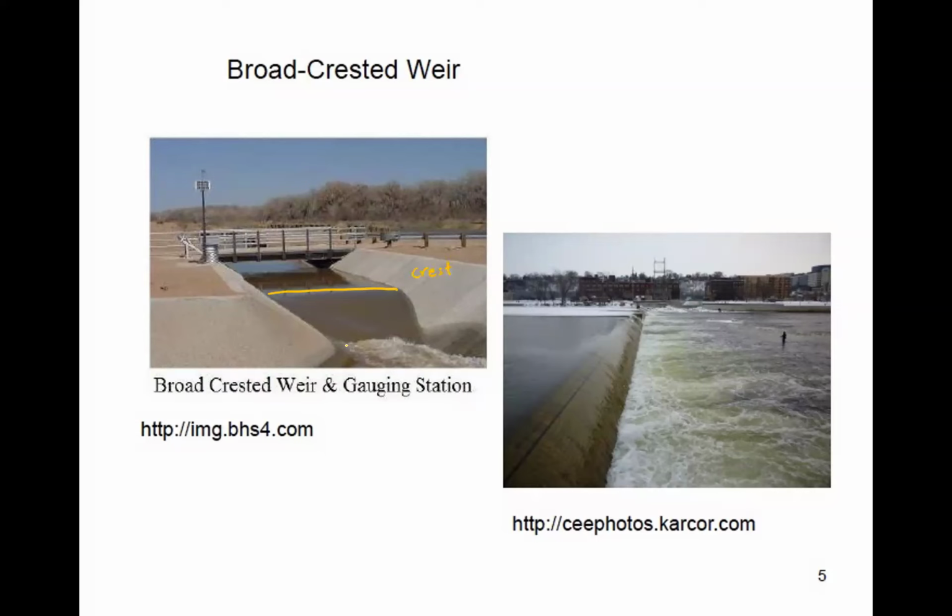And by the way, you see there's a hydraulic jump here as well. Not surprising. We saw the exact same setup in the case of a hump, right? If you choke the flow upstream, you have subcritical flow that accelerates, becomes critical, continues, most likely becomes supercritical, and depending on what's happening downstream, you may have a jump. This is the case in this image.